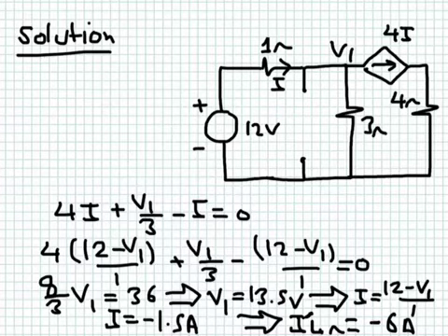Okay, so what I did here, I removed the current source. The current source has been removed, it's open circuit. I kept the voltage source. I now have to find the current here due to the 4 ohm. I have only one node and ground in this circuit, so the easiest way to do it is to simply apply nodal analysis.